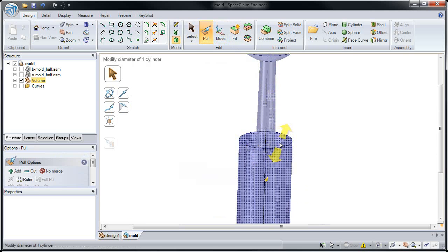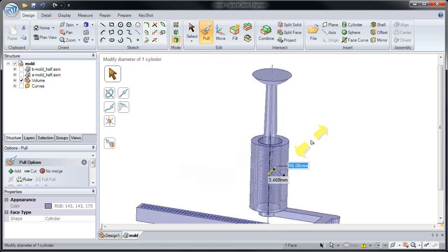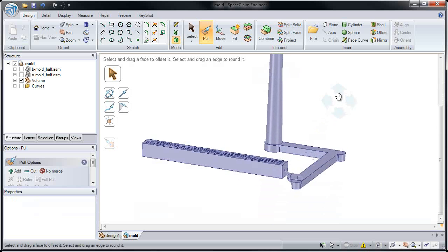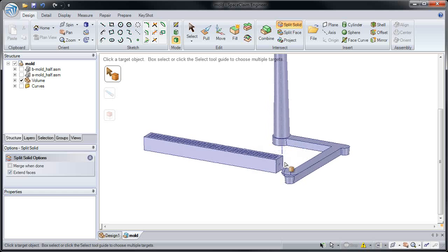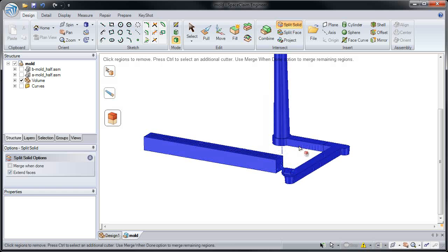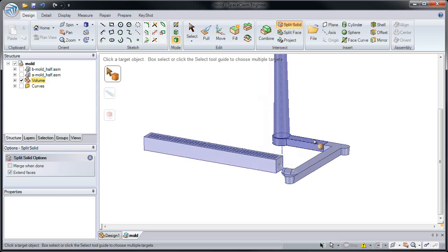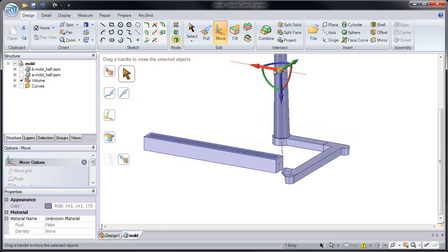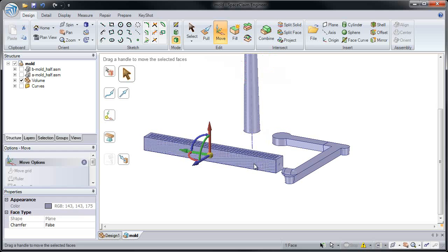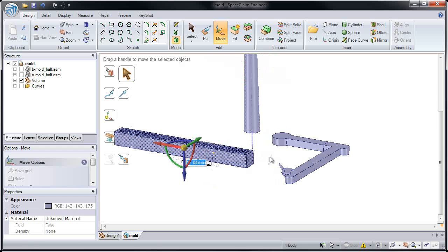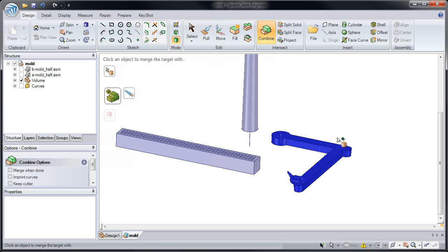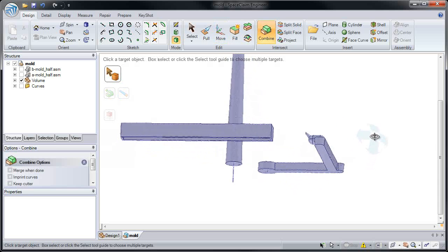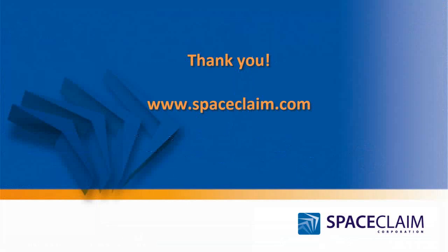Now after we create this, it's just a solid model, so we're still able to pull on it, fill things, and make any changes we may need to make. For example, we may take that plastic and split it up into different sections to break up our analysis. Focus on the inlet model, focus on the cavity, or focus on the area in between. I hope you've seen how SpaceClaim can be used to quickly and efficiently edit parts and assemblies to prepare models for moldflow.